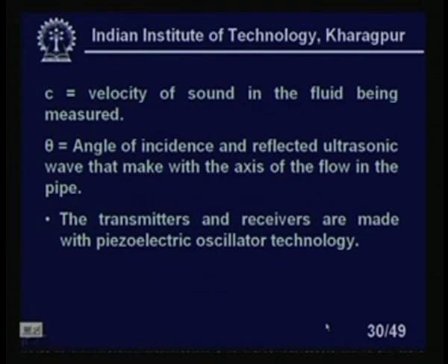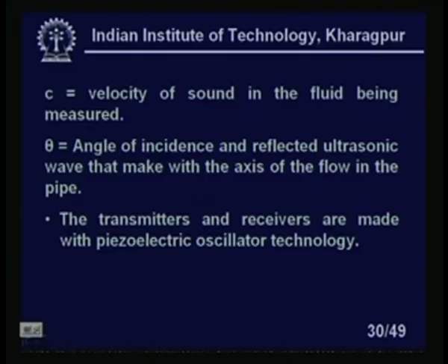Now you see here we have to know c very accurately in the medium itself, okay, because the accuracy of the entire measurement depends on how accurately you know the velocity of the ultrasonic wave in that particular liquid, right. That is to be found earlier, then only you can find the velocity. But in some other methods this is not necessary, it will cancel out, right. Those methods are preferred.